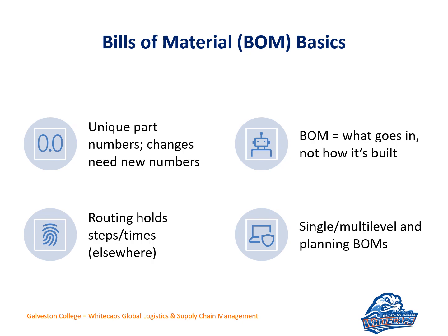If there's ever any revs and you received it on the floor, one manufacturing process we had to put in place before it got automated was that when they started a manufacturing step, they'd have to look at the bill of materials and check our database to make sure it was the most recent. In fact, every handoff at every step, we had to check that. It created a few unique problems when that first step was not done.